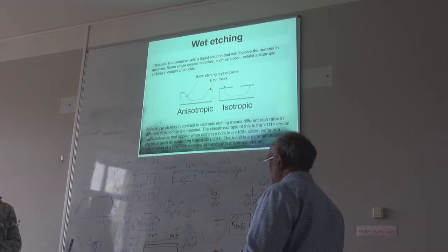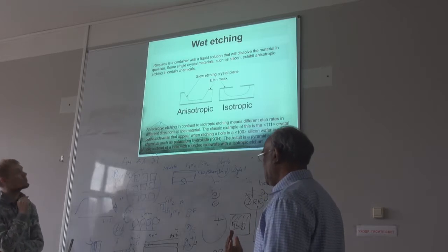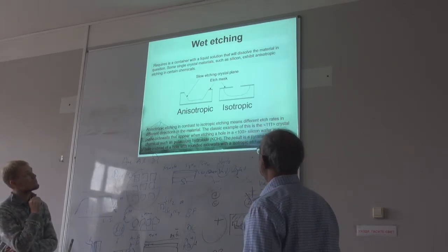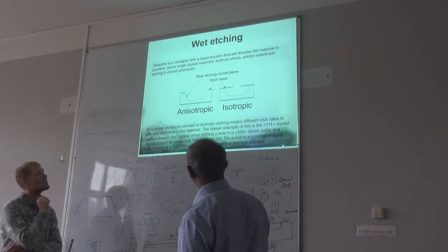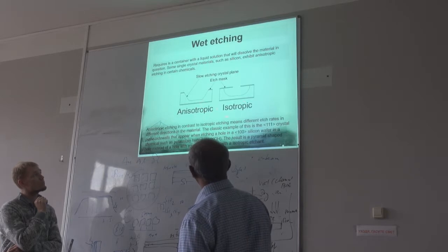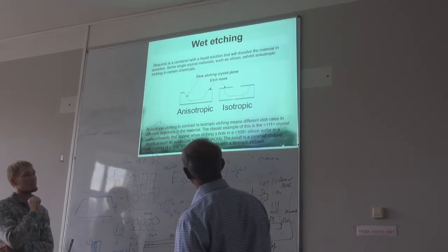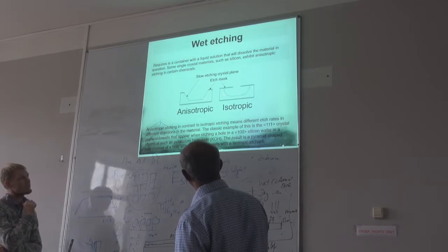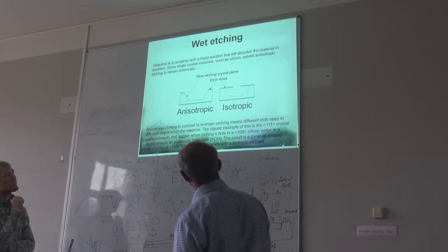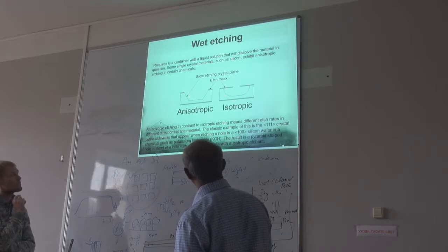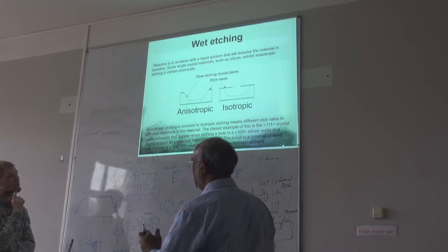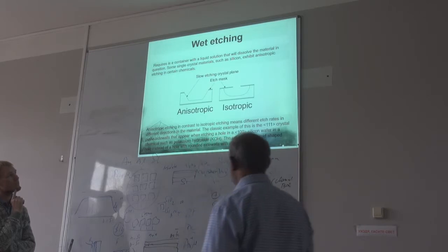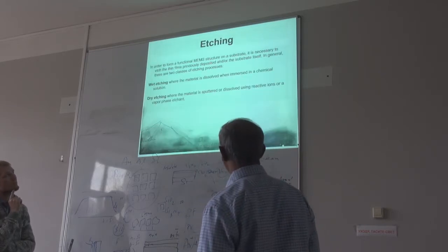So if you want to etch deep into the substrate, then you have to use DRIE. This etching can sometimes be anisotropic or isotropic. Anisotropic means you need a kind of uniform etching like this, not like that. Typically we call this the undercut, and this depth should be pretty much similar in size. So these are some tricks here.